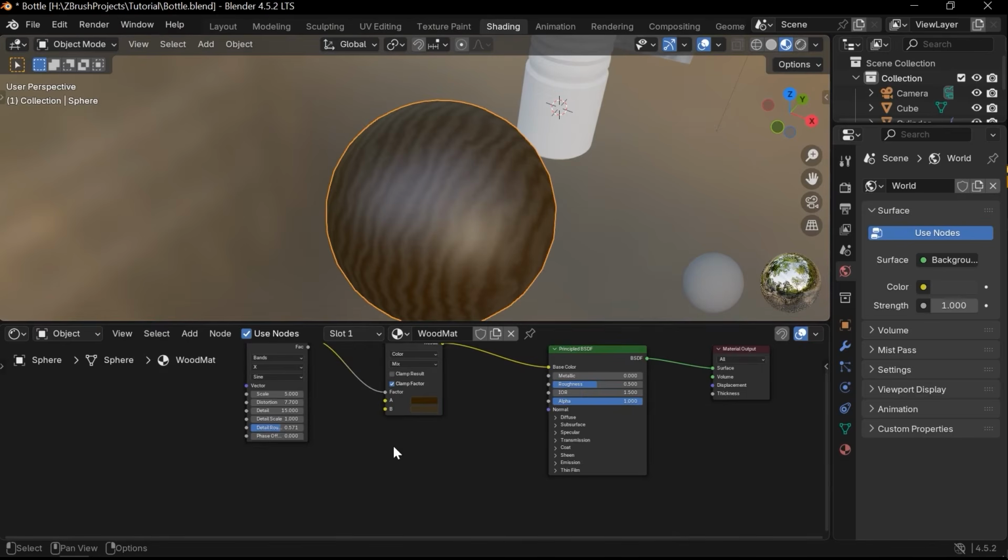Actually, when you make your textures in Substance Painter, ZBrush, or even Blender, and export your textures, you have PNG, JPG, or TIFF files. Your normal map looks like a combination of purple and blue colors, and you simply connect your blue and purple texture to the normal map, and you can see some bumps will be added to your surface.